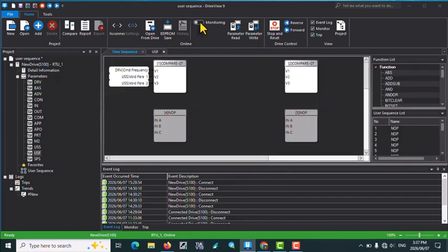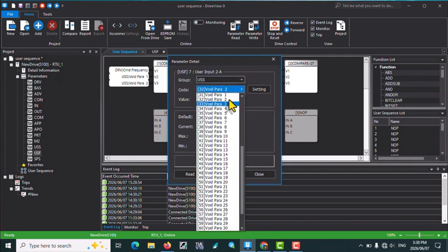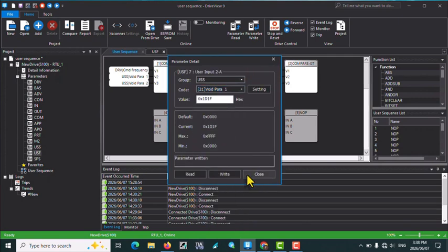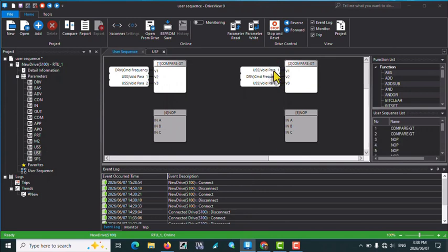Now I go to the user sequence section. Now it's set up so that if the parameter is... Alright, here, parameter 1 should be selected. I had put 2. If my parameter 1, which is 5, as long as it's higher than my frequency command, the value of my 600 hex address should be 1, and this inverter will stay stopped until my frequency command passes 5 Hz. It will execute this function and assign the value 2 to the 600 hex address.